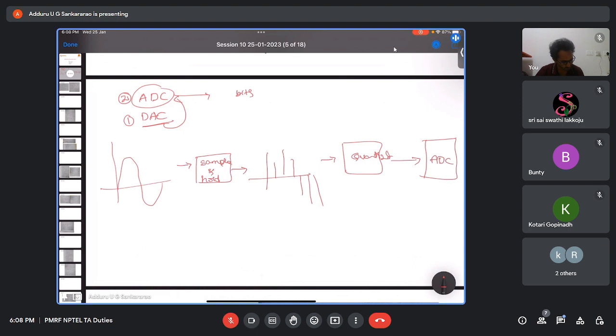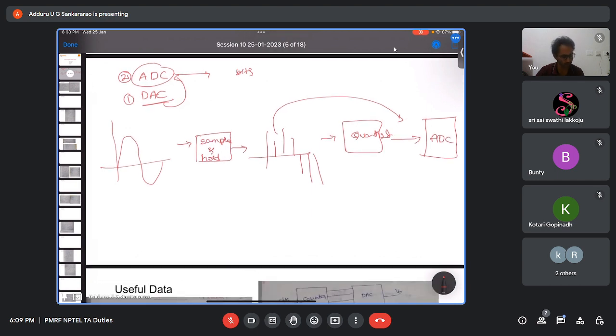That means whatever we are giving to an analog to digital converter is not the continuous signal directly. We will give the sample only. The sample value is converted into the form of some bits, 0010, something like that. Let us say TS is the sampling interval. To convert one sample, the analog to digital converter takes some amount of time. We say conversion time, TC, let us say.